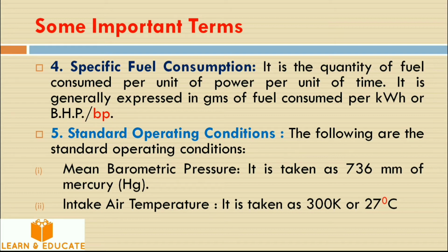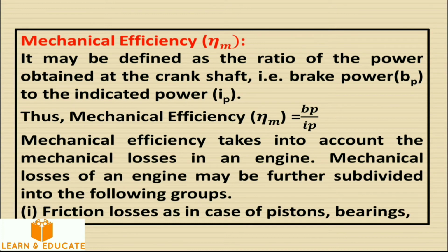Now let us state the standard operating conditions with regard to the engine. The pressure is taken as 736 millimeter of mercury and the intake air temperature is taken as 300 Kelvin or 27 degrees Celsius.